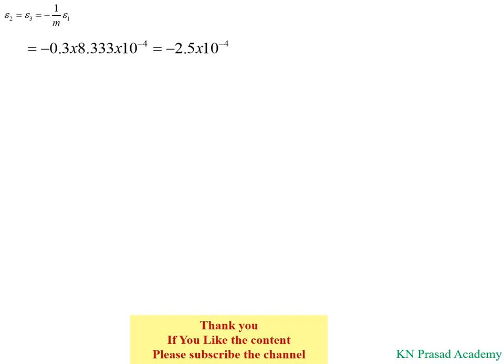So the strain is minus of epsilon 1 divided by m. Here 1 by m is the Poisson's ratio, already given in the data, 0.3, and epsilon 1 we have calculated, the longitudinal strain, 8.33 into 10 to the power minus 4. So epsilon 2 and epsilon 3 values are minus 2.5 into 10 to the power minus 4.